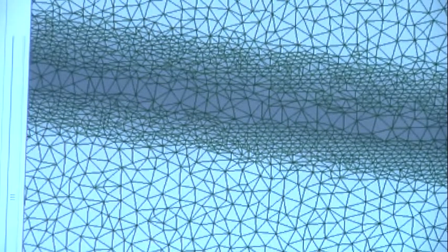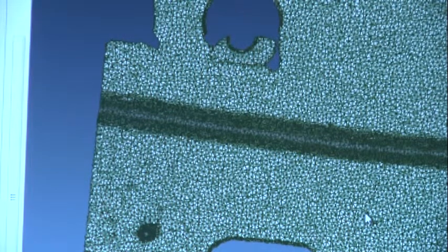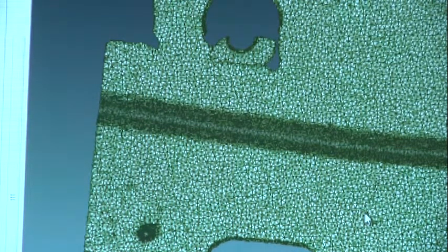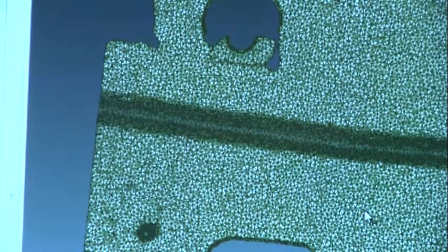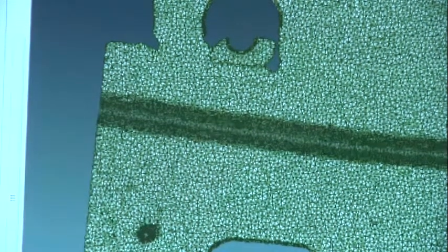And in this case, there's also a maximum edge length in order to prevent having only large triangles, because for inspection, you want to keep data in order to be able to fit your planes or your entities on it. So that's for the parameters.